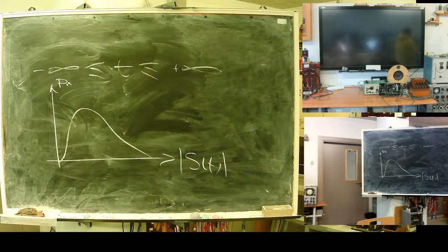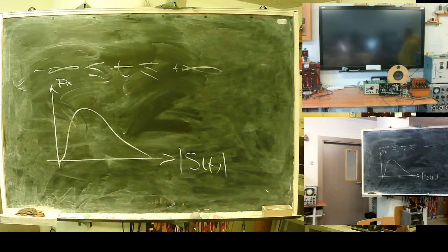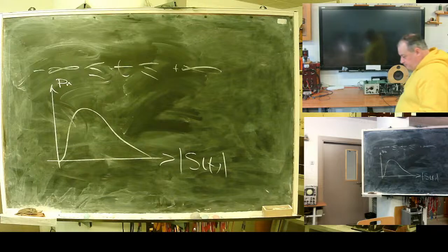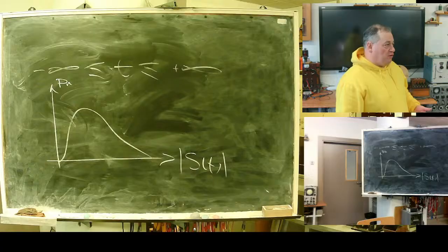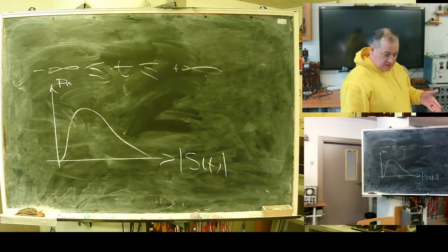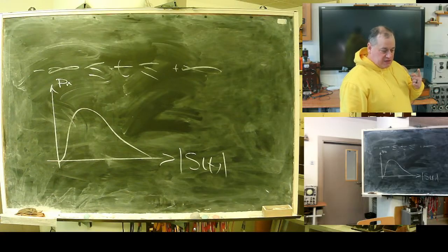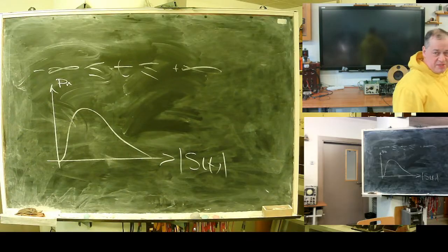In my case, power system protection, I need to guarantee that my device will be operational during an expected system fault. This means that my device, if it operates by current, with a rated current of 5 amps, should withstand 200 amps within 5 seconds.